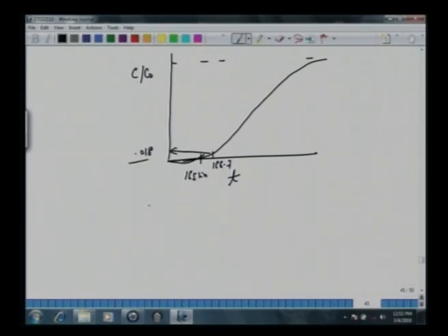So this is 166.7. That means as per our definitions, we can say that very close to this breakthrough time TB is 165 minutes. So going back to the previous data, at 154 there was 0 response, then at 167.7 we have 0.018. One can do this interpolation to obtain that the breakthrough time is around 165 minutes. Okay, and then at 350 minutes the bed has become saturated.